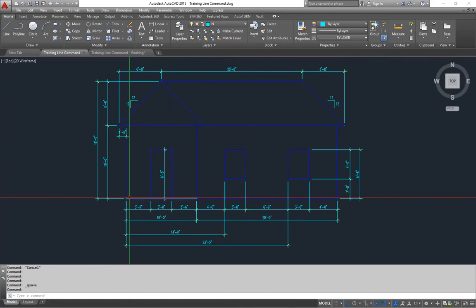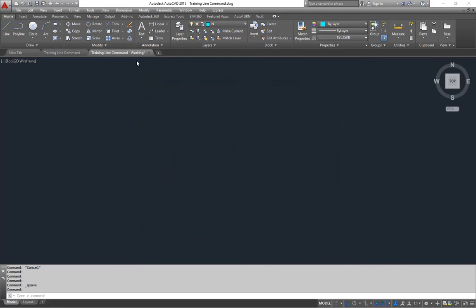So we're going to start at the absolute 0 coordinates in AutoCAD and draw this box. So to specify the point, it's an absolute location. I'm going to draw a line, L, enter. And then to specify that point, you have to specify X and Y coordinates. We're leaving Z out of it. We're drawing 2D right now, so all we're going to talk about are X and Y coordinates. This is using a standard Cartesian coordinate system.